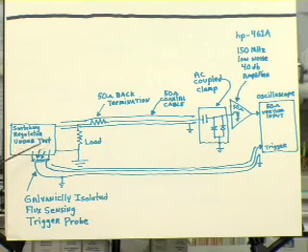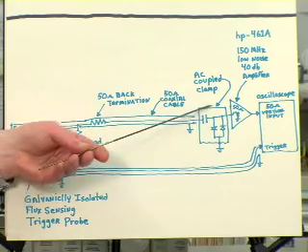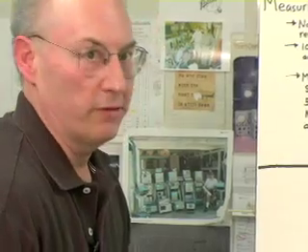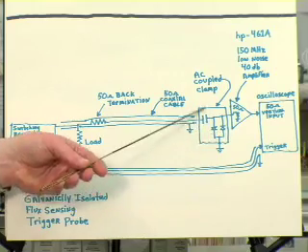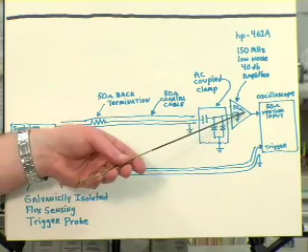Dropping down to the bottom of the page here, the switching regulator is represented by this box to the left. We institute a 50 ohm coaxial measurement path with a back termination out of the switching regulator's dummy load, down a 50 ohm cable, through this AC coupled clamp. What's that? That's basically a capacitor and clamp diodes in a 50 ohm coaxial enclosure in front of the preamp.